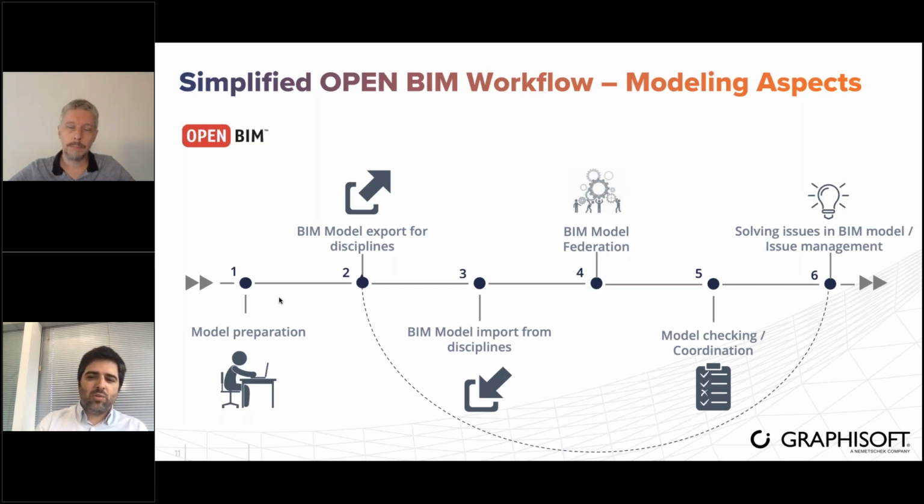When we import, we should also do some proper mapping of materials and classification, so that the elements go through properly. When we federate elements, we also need to know what the correct process is. Should we open an IFC directly? Should we put it on a blank file and then just link it into ours? There are many ways that we can do this.